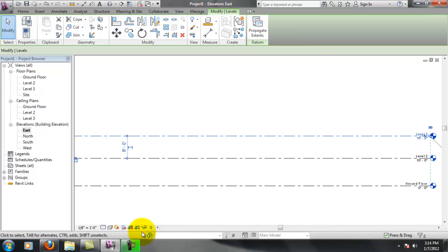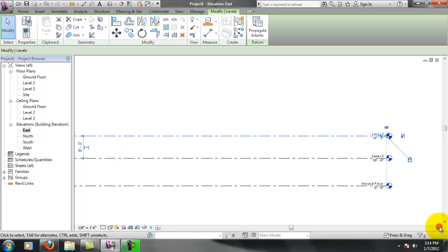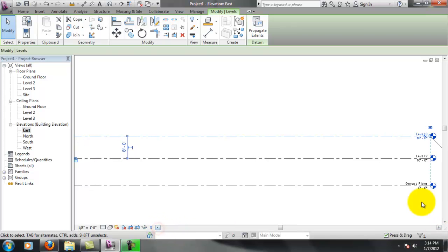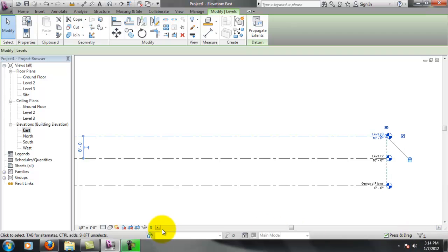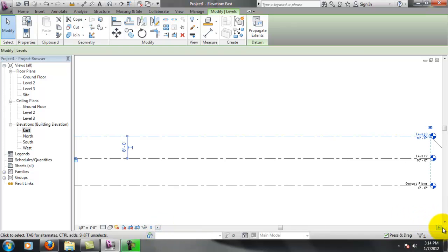It's not like AutoCAD where you have a command line down here and you type in polar coordinates and so on and so forth, which you could go into the relative coordinate system, Cartesian coordinate system, or whatever, but Revit doesn't function that way, mainly because there is no coordinate system in Revit, which could be a little confusing at first. There is no 0,0 in Revit until you get into creating your own points. When you need to import AutoCAD files, you'll find sometimes when you're trying to correspond with site or even structural or civil engineering, you're going to need to create a temporary coordinate system, and you can do that. But by default, there's no coordinate system. So in Revit, everything's done off of these temporary dimensions.